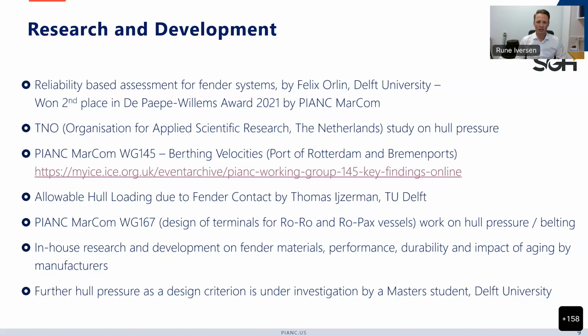TNO in the Netherlands have done several studies on hull pressure. I already mentioned PIANC Working Group 145 on berthing velocities. We've done studies on allowable hull loading due to fender contact. There's actually two master's theses that have dealt with that subject. We have considered work from PIANC Working Group 167 for design of terminals for RoRo and RoPax vessels on hull pressure and belting. And then also in-house research from the fender manufacturers on fender materials, fender performance, fender durability, and impact of aging.